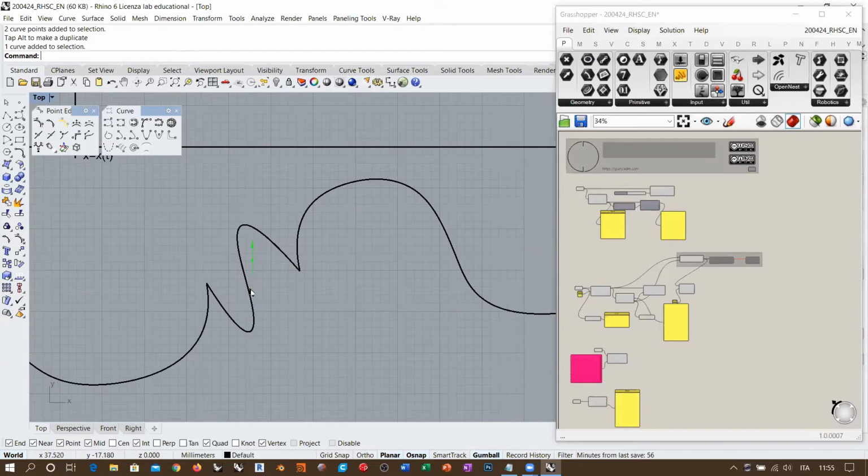So I can work with direct control point modeling. In this case, I cannot define exactly the precise continuity level from curvature up. I cannot do this. So I have to use utilities, which are, by the way, blend curve, match, and so on. But I can provide the right topological structure, meaning the right amount of control points in order for this curve to become tangent to the existing ones, okay?